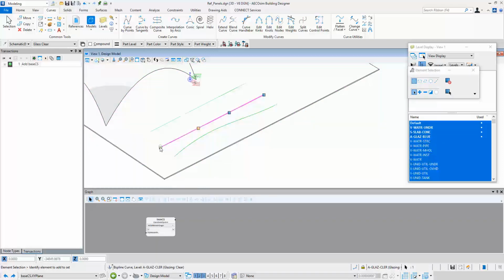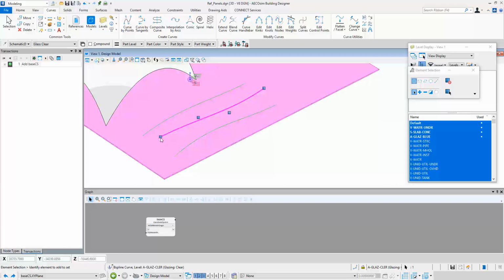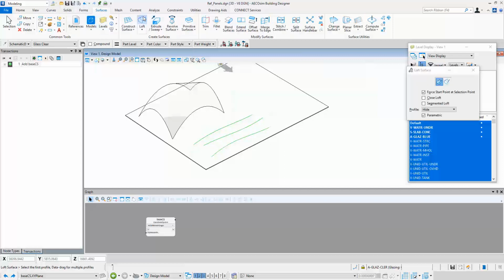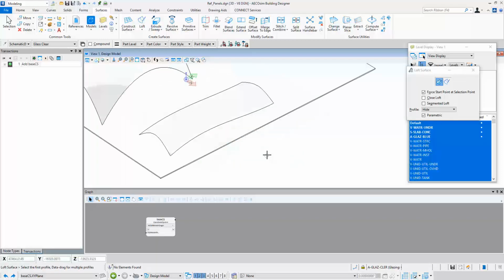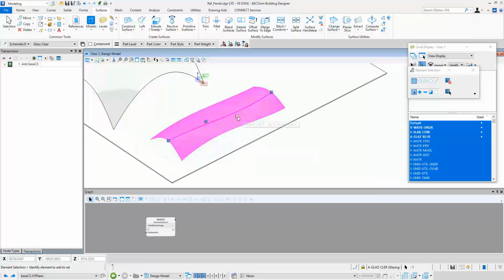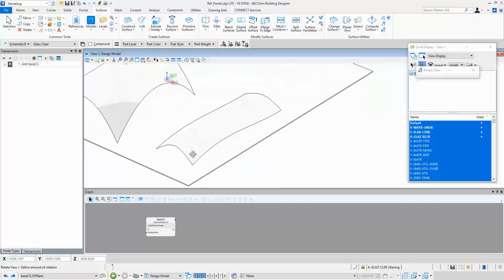Again I'll hold down the control key and loft these two up like that, and with the same, I can pull this one up a little bit too. Maybe at the end, just so I've got a bit of an entrance to this canopy, I can loft that one up a little. Back in our surfaces tab, we can use the loft surface command, run a line over the top, and we've created ourselves a little surface. Now, these surfaces have complete history. If I click on them, little widgets appear, and we can start to change the overall form of the surface by moving these widgets around. So we've got a couple of surfaces here like that.